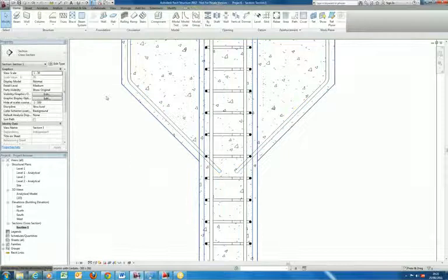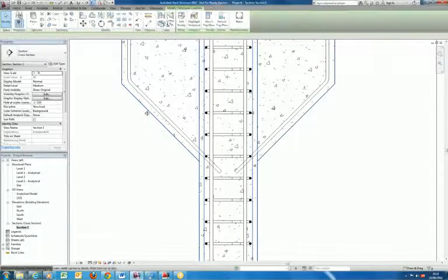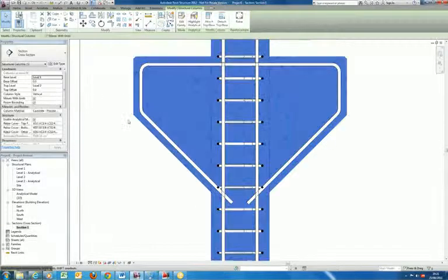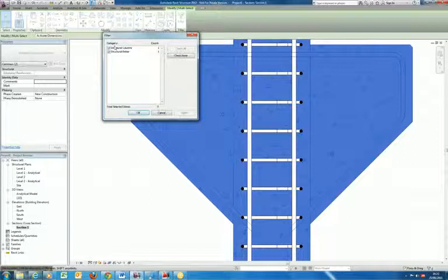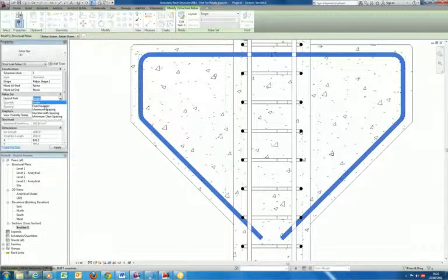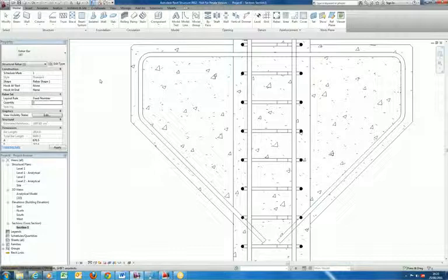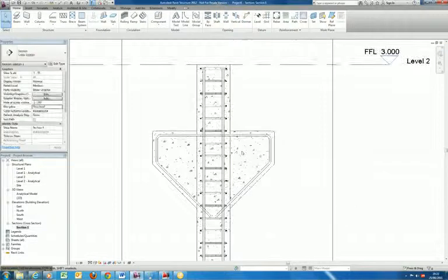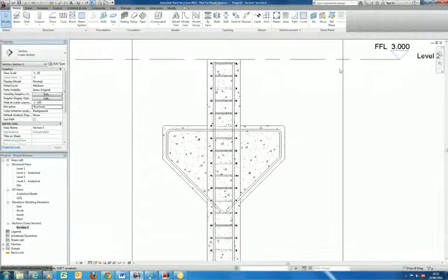Again, the number 3, so I'm going to pick the bar up. I can use my filters very easily to actually pick that out, so I'll say rebar, and let's change that to a fixed number 3. Finally, I'll add one more custom area in from the core build to make sure there's a good attachment.